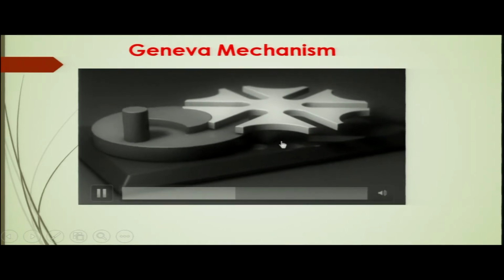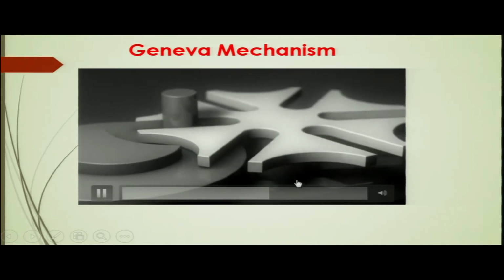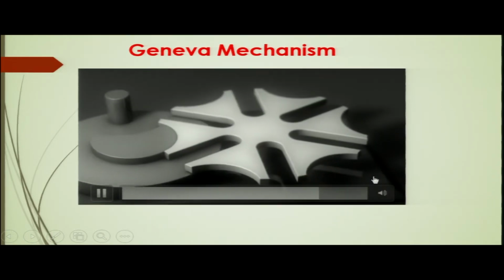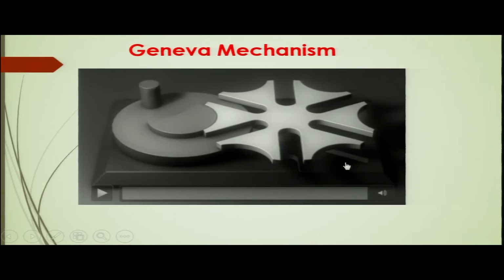So, sub assemblies will be located directly on this position, and here we will have the machines. So, machines are not located on the Geneva wheel as it is, but the sub assembly has to be here. So, the load of the sub assembly will be on this Geneva wheel, and with this load this pin has to be able to move that much load from one position to another position. Okay. So, the pin becomes the weaker point in this case. For any reason, if the pin breaks, in that case the mechanism collapses and it cannot work, as you understand. That is the first drawback of the Geneva mechanism.